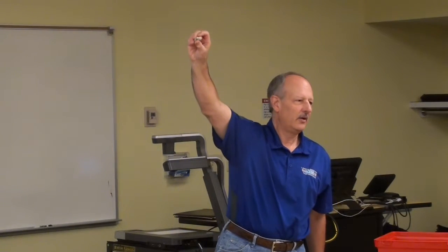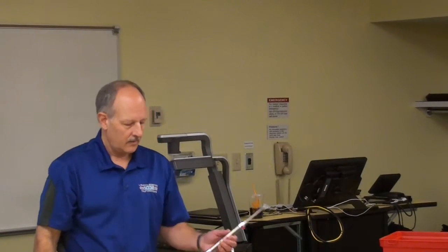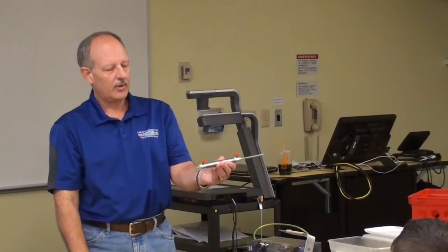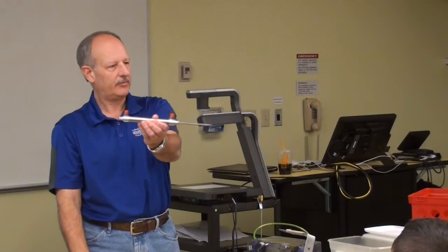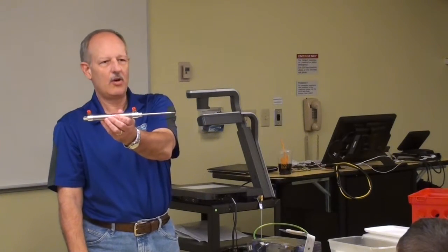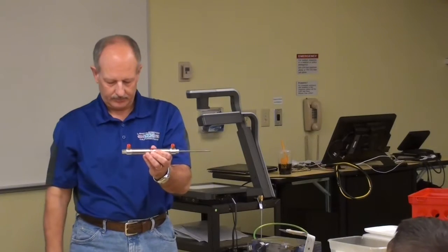Okay. How many people know what this is? It's hard to see. Flow control. So why do I need flow control? What do I use it for? To change the speed of your cylinder, whether in or out. Okay, so here I have a cylinder, right? What limits the speed of the cylinder? The output air pressure. Airflow. The bore. Airflow going in, so the faster I can put air in there, and airflow out.